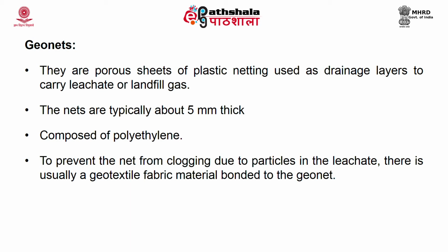So, sometimes geonet is bonded to a geotextile fabric. If you look into the pore size, geonet will have a slightly higher pore size than geotextile. So, if you bond a geonet to a geotextile, what will happen? It will again further remove some of the bigger particles which are there in the leachate, and the further removal can be done by the geotextile fabric.